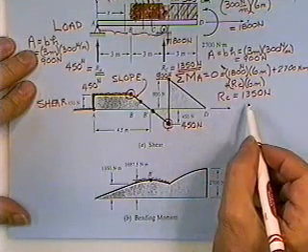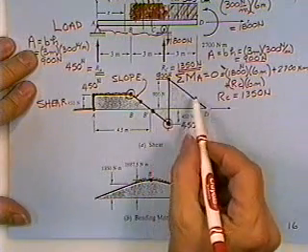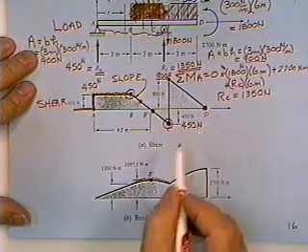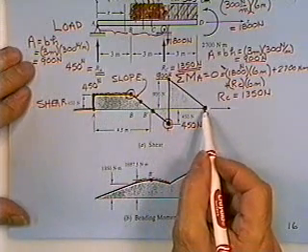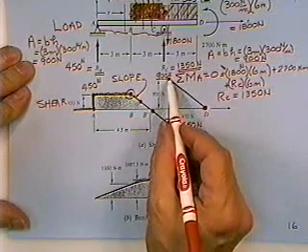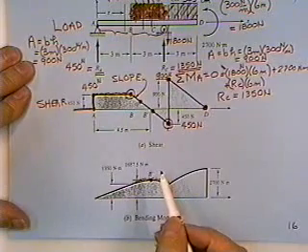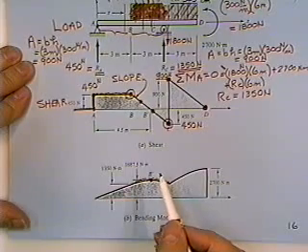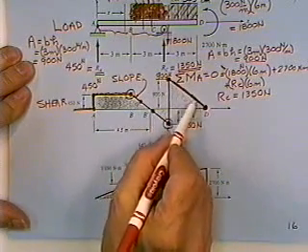So if we're going to go 900 newtons worth of area down, and we're 900 above the line, that makes it nice because these shear and moment diagrams should close on 0. You start on the left-hand end at 0, you work over to the right, and they should close on 0. Now then, we know there's a point 900 newtons and a point 0. The question is how we should connect the 2 points. We go to the mathematician. He says straight horizontal lines turn into straight sloping lines. So we simply connect the 2 points with a straight sloping line.